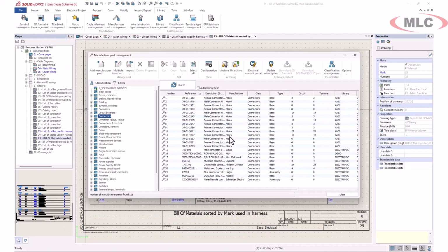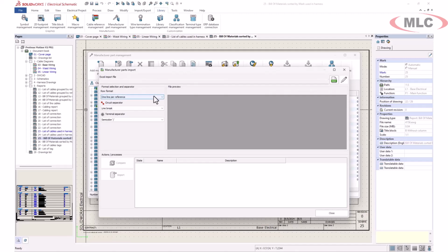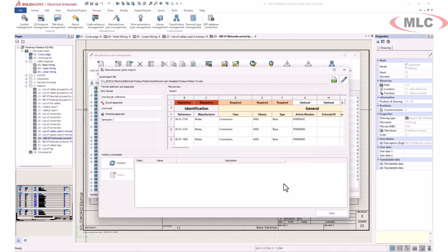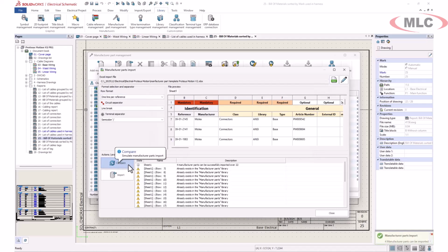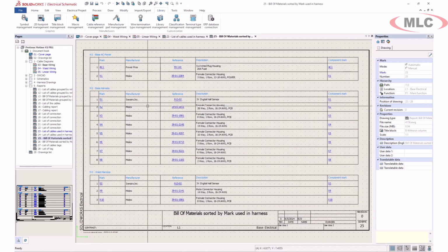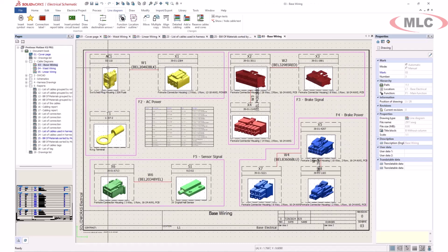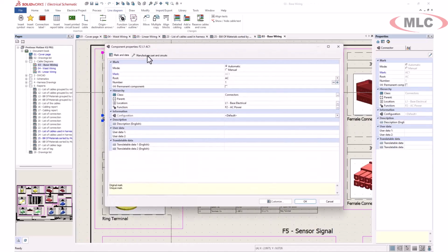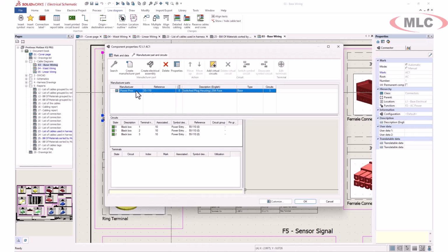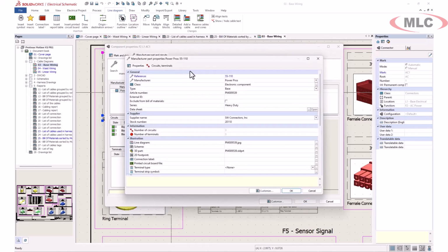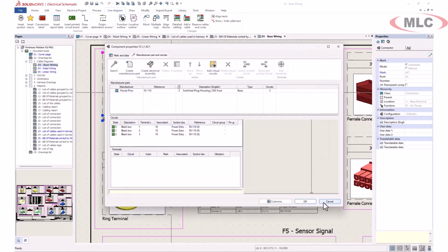Manufacturer parts can be defined, including the circuit and terminal details. Note the use of different separators for both circuits and terminals within those circuits. With this import tool, you can quickly add your exact content with all the possible details to the library, like this fused power plug AC1. Like I mentioned, Excel import extends to cables as well, and I can define them completely with cable cores.